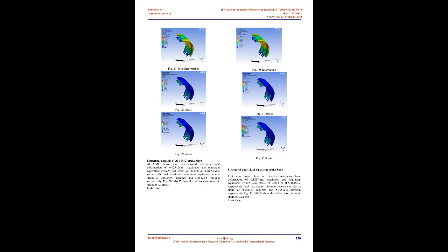boundary conditions, collectively referred to as pre-processing, the solution of that mathematical representation, solving, and the study of results of that solution, post-processing. 3.1 Structural analysis of brake drum. A. Import model. In the pre-processing stage of FEM, the brake drum and shoe geometry were imported from CATIA V5 into ANSYS 14.5 Workbench as shown in Figures 3 and 4 respectively.